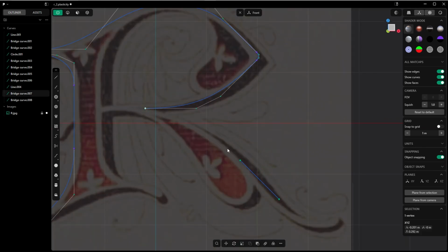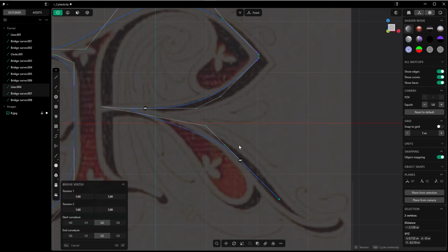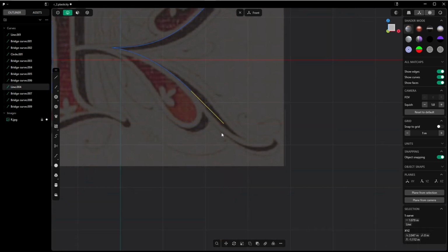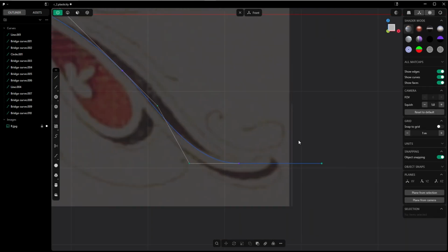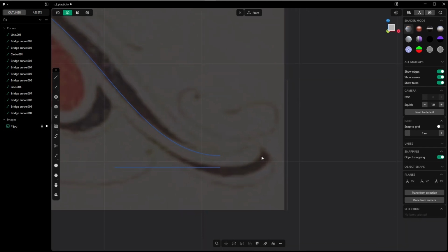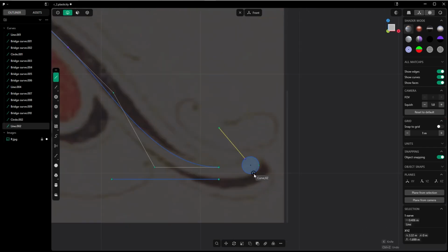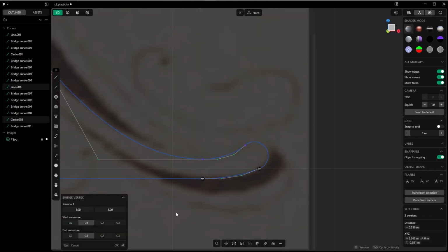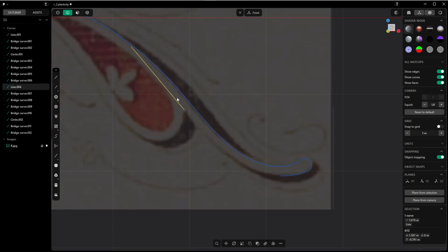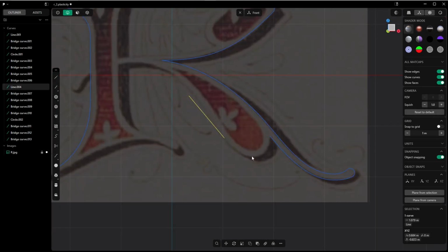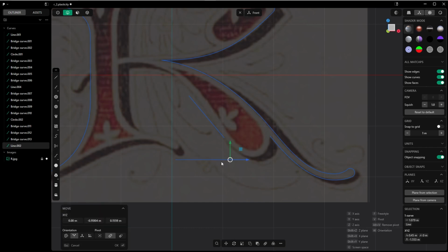So let's loft these two control points, pressing L, and this time obviously I need the G0 continuity at this part, and here G1. Yeah, that looks cool. Let's play nevertheless with the tension. Let's keep on lofting. This tutorial contains obviously lots of repetitive actions, so there is no point in showing these actions in real time. In this case, you know the deal. Use a line to create lofts between the line and the curves you have already created.